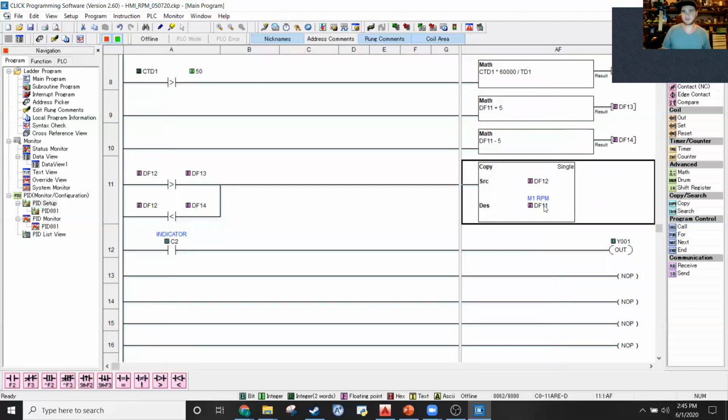And I know going through this exercise, I've basically buffered that so it's a semi-stable value. Because it's really important, well, there's different ways of filtering your input in a PID loop. This is a manual way to do it. There's actually conditioning you can program into the loop, but it's kind of important to make sure, like if your process variable measurement is jumping around like this, your PID loop is going to jump around trying to compensate for that, right?